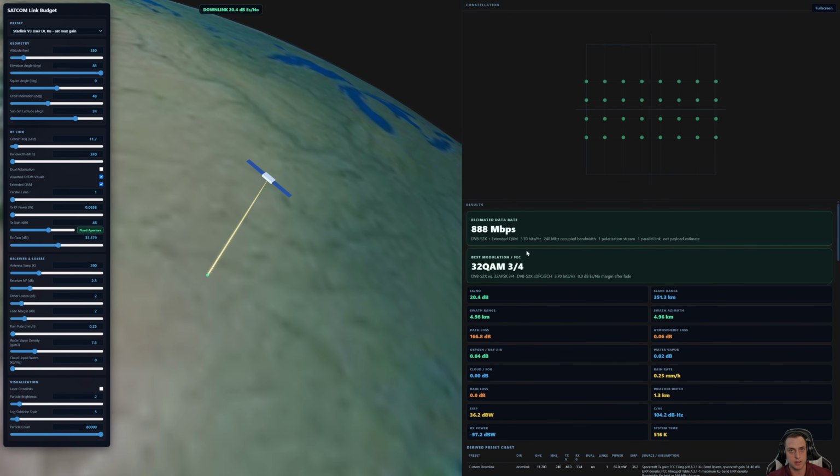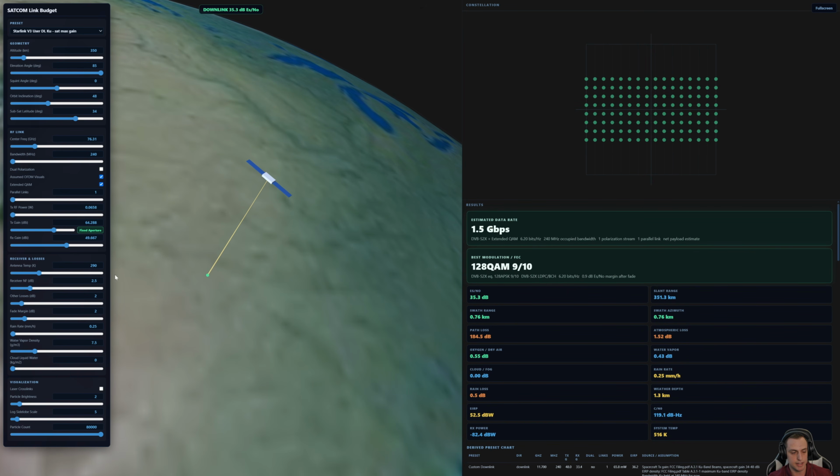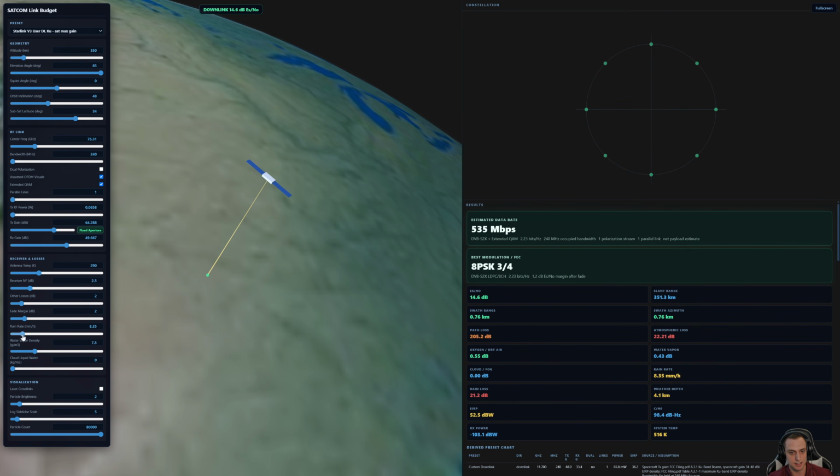So to use more bandwidth, you need to either use more antennas at different center frequencies and/or use higher frequency antennas. So for example, at Ku band, this is centered at around 12 gigahertz, and so they can use around 3 to 4 gigahertz between uplink and downlink. As we move further, say V-band can use up to 10 gigahertz. And then out at W-band, these are their special backhaul antennas. These can use around 20 gigahertz. The next limitation on bandwidth is the atmosphere. So that's the atmospheric path loss that was in that equation we covered earlier. At somewhat low frequencies like Ku band used for the Starlink user terminals, there's not very strong atmospheric effects in most cases. However, if we move up in frequency, you can see that we can run into some problems. For example, here we run into an oxygen absorption band. That's going to basically completely block our signal by the atmosphere. As we move up, that'll mitigate. However, when it starts to rain, that can have a significant effect and it can potentially completely knock out your signal.